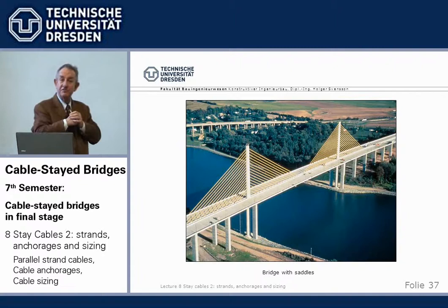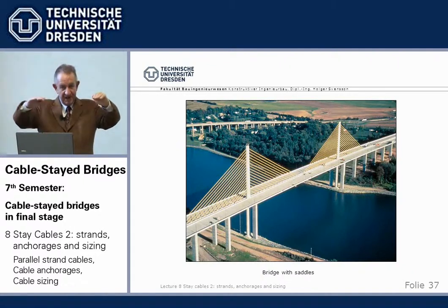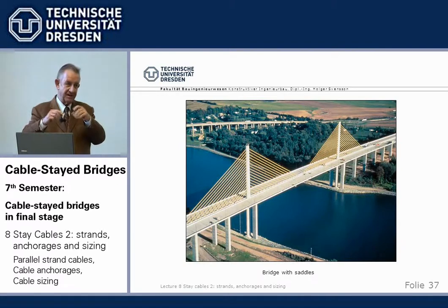What about the fatigue strength now in this clamped cable? With suspension bridges we were not interested. There's a different situation with the stay cables. Well, there were first initial tests made, and they failed, and no good, and we were thinking about it. Finally, by making the ends curved, so that there is a gradual force increase in the saddle, and all sorts of tricks, people succeeded in getting the fatigue strength also for saddles, okay?